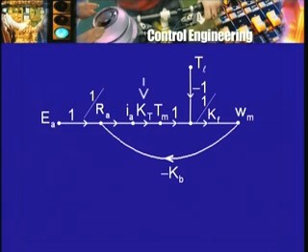multiplied by Kt is the next signal that can be identified as the motor torque. Then we have the load torque as another node. So coming from TL with a gain of minus 1 and from Tm with a gain of plus 1 is the next node, and the node signal here can be identified as the torque required to overcome friction.